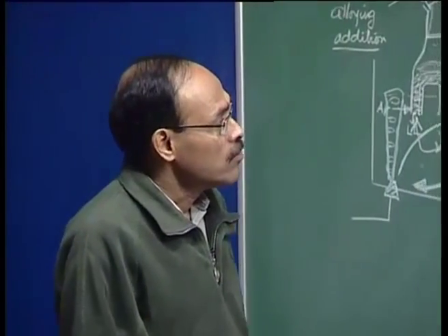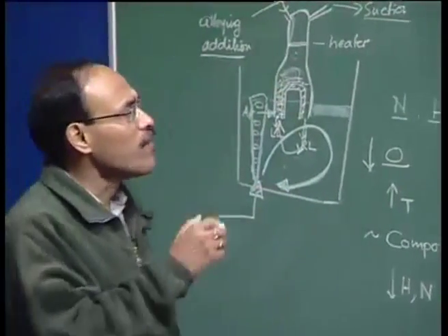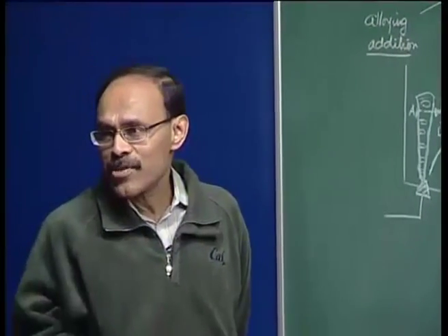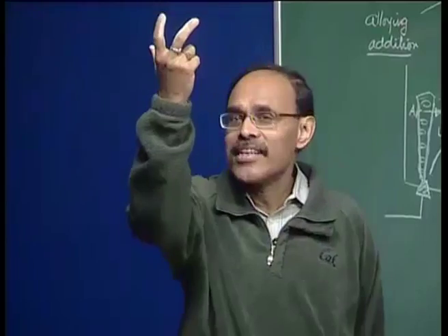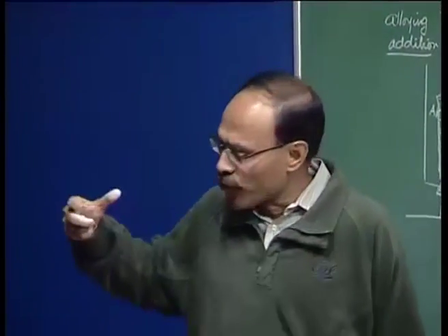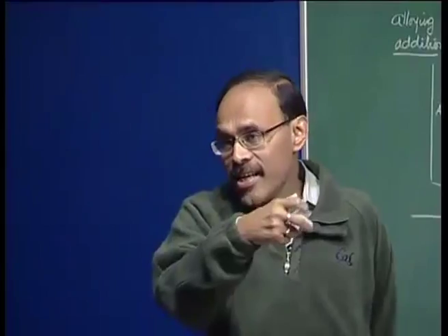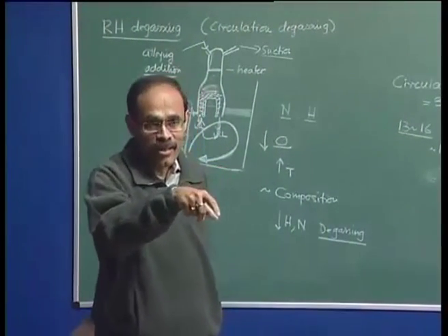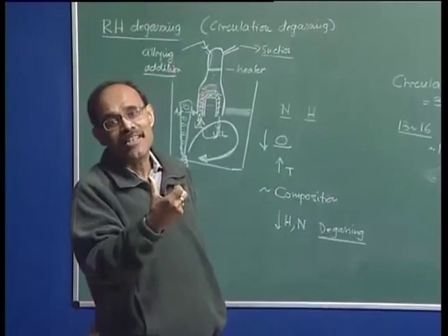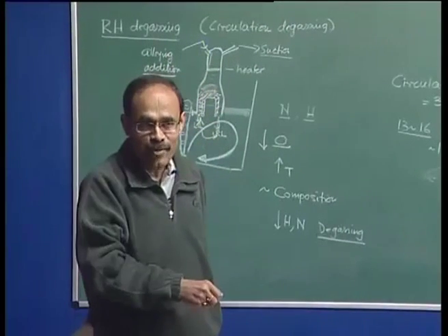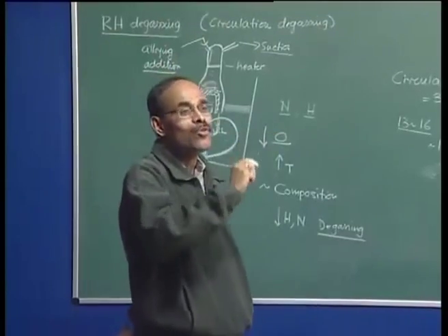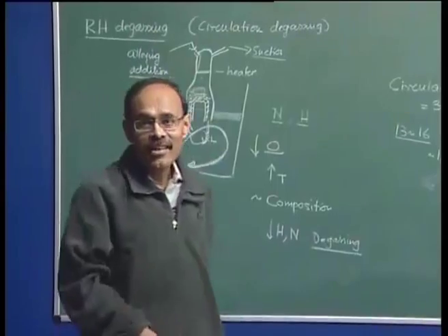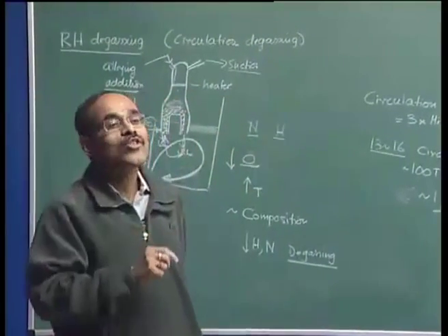Now, the slag is not really very basic, and sometimes we cannot have too high a temperature in the blast furnace. If the temperature is too high, to make the slag fluid and to drive the desulfurization reaction from left to right, we experience too much silicon in the metal, because the silicon reduction reaction takes place at elevated temperature, since there is a lot of coke in the blast furnace. As a result, the pig iron is going to contain a lot of silicon, and that silicon is going to drastically affect the performance of the oxygen steel making processes,